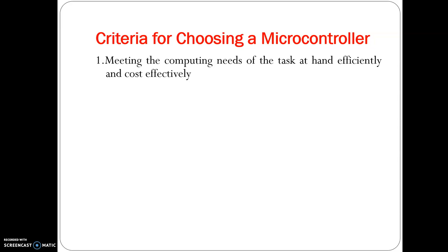This is the first and foremost, the most important criterion in choosing the microcontroller. In analyzing the need of a microcontroller based project, we must first see whether we need an 8-bit, a 16-bit, or a 32-bit microcontroller to handle our computational need effectively.